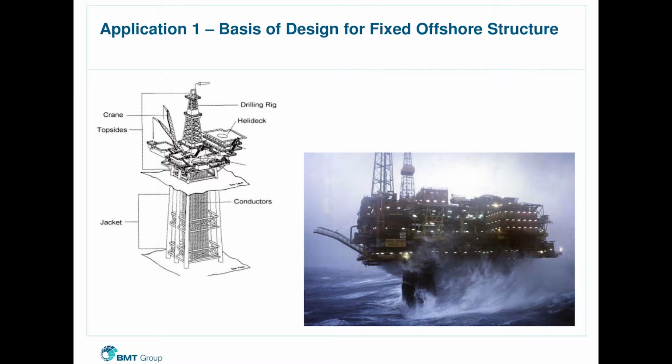So I'm going to look at three applications here. The first one is a conventional fixed jacket offshore structure. So this can be a steel or a concrete substructure on the continental shelf at water depths of a few tens of meters, limiting depth perhaps just about 100 meters.